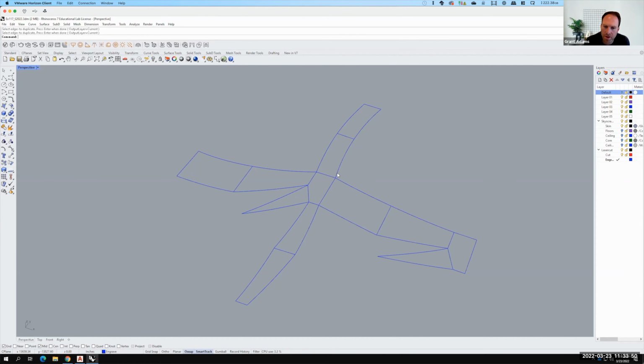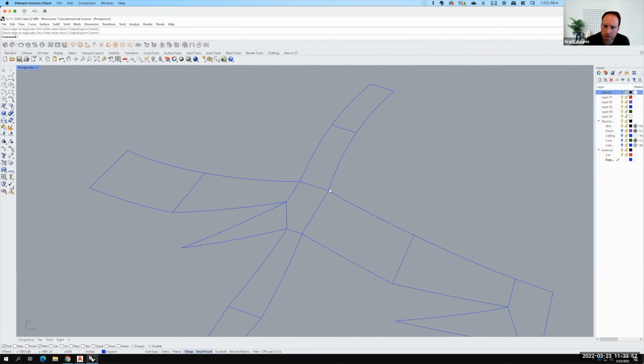So when we think about cutting this out, it would be really helpful to have some kind of a little gluing surface to tab the two together. So if I was going to create that gluing surface, I really need to offset one of these to create that little bit of a tab. So let's use an offset. I'll type in offset, and my distance here is probably going to be somewhere in the neighborhood of, I don't know, 25 feet. We'll try that.